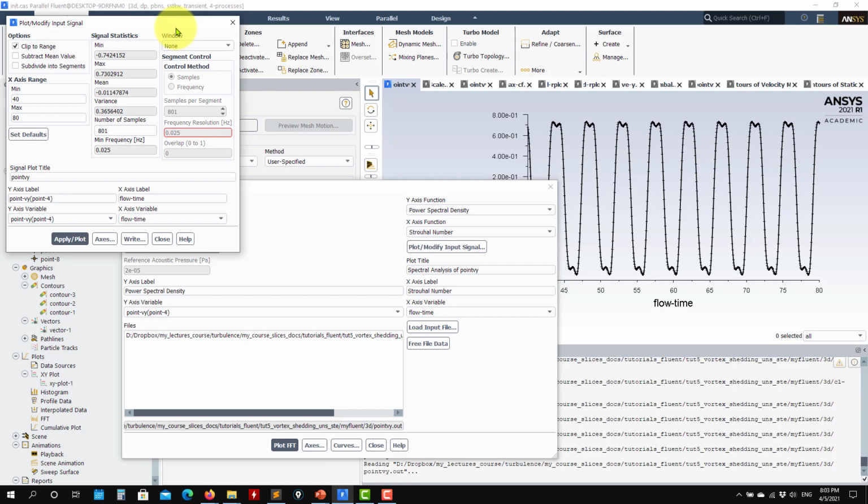Here we have the instantaneous velocity. If you want to get the turbulent kinetic energy, you need to get the fluctuation, and remember that fluctuation is instantaneous value minus the mean value. And remember that we're computing statistics, so you can do instantaneous minus mean, and you get that fluctuation that actually you have it here.